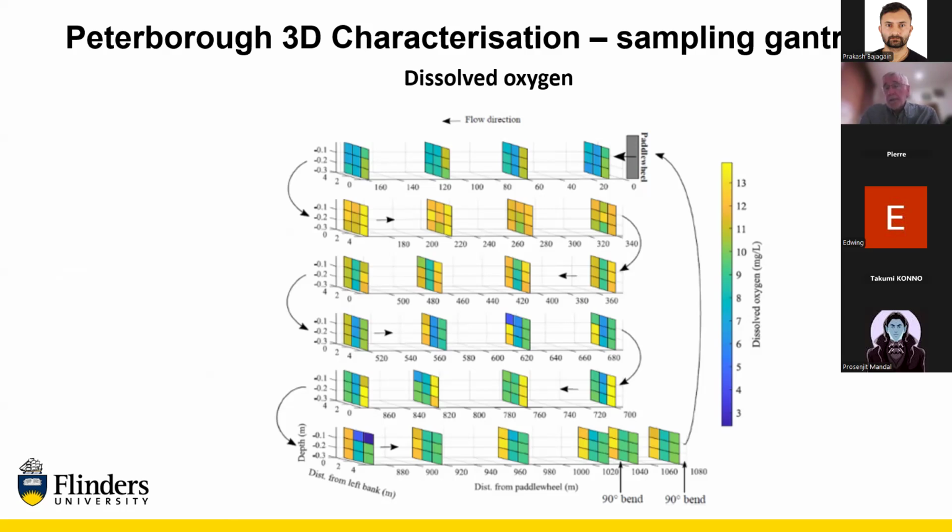What I'm getting at is we're taking 12 hours to do this measurement. And over the day, if you've got sunrise, irradiance increases in the morning to a peak in the afternoon, and then decreases, in our case, probably about 3 o'clock in the afternoon, the irradiance decreases, and it goes to dark at 10 o'clock at night or whatever. And over that period of time, dissolved oxygen is naturally changing because there's more light available for photosynthesis.